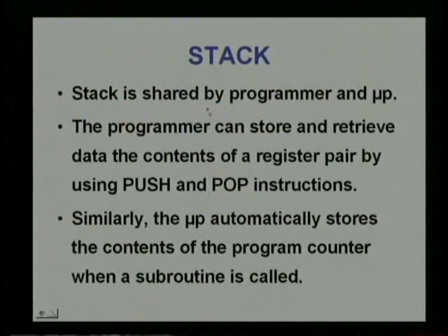Next, stack is shared by programmer and microprocessor. Programmer, as and when he needs to store some of the register contents in the memory, can store them by using instructions like push. And microprocessor also stores the addresses whenever it executes instructions like call.